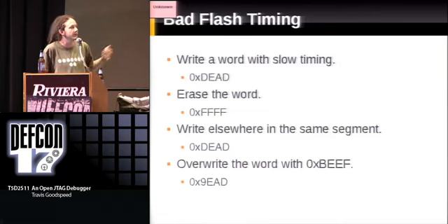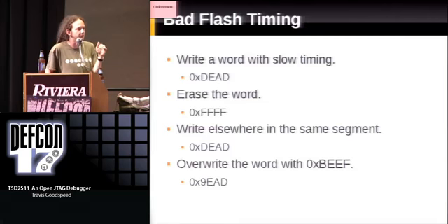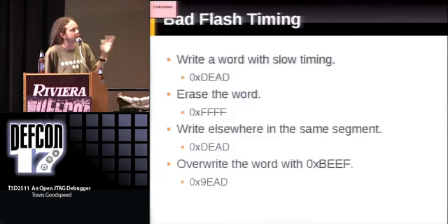But this is after an erasure. This is after the programmer assumes that the region has been cleared. And this would even have passed a verification for the erasure, because just after the erasure, it was ones. It would not pass a verification after the second word had been written, after BEEF was written. So it might be possible to turn this into a sort of exploit.